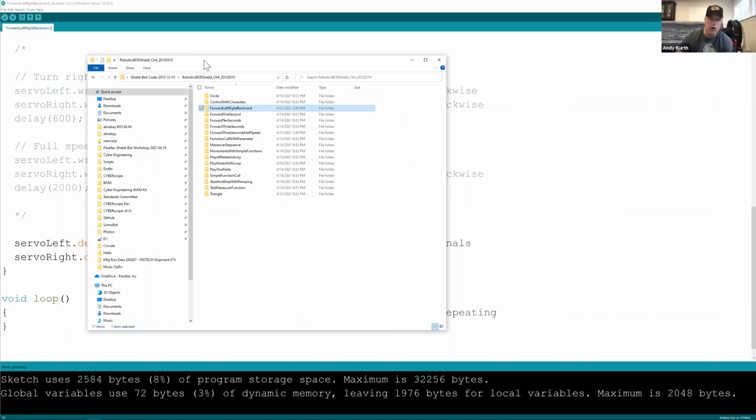However, in Arduino, it doesn't matter. In Arduino, they declare the function prototype for you, but don't show you that it happened. They take care of that step. And so my point of curiosity is, if I declare it again, I don't think there's going to be a problem, but I wasn't 100% sure about that.